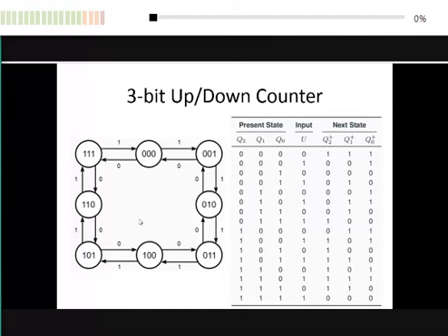All right. So how are you going to use it? Wait, haven't completed yet. You must use 3 units of 16 to 1 multiplexer. Why 3 units? Because 1 unit for Q2, 1 unit for Q1, 1 unit for Q0. I think there will be one example there later on. So your development cycle is very fast because you don't need to do the K-map.